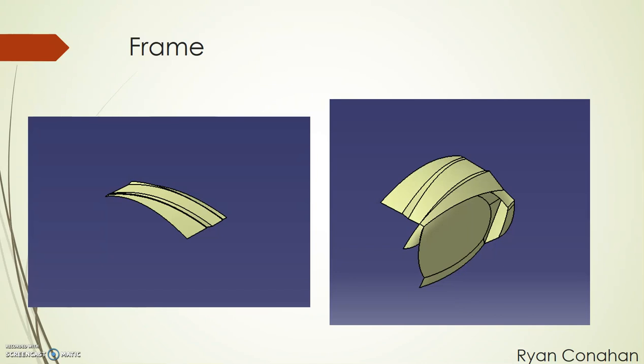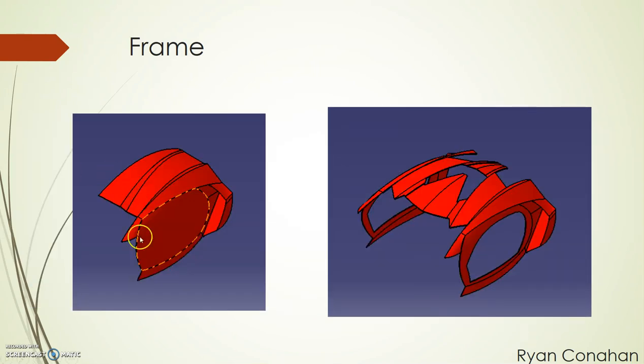So we start with the midsection, and from the midsection start the roof. The roof composed mainly of spline tool, and then from the roof worked on the side of the car, which was also spline tool with the addition of coordinate points. After doing that, we filled that and thickened it. And as you can see right here is the thickened product.